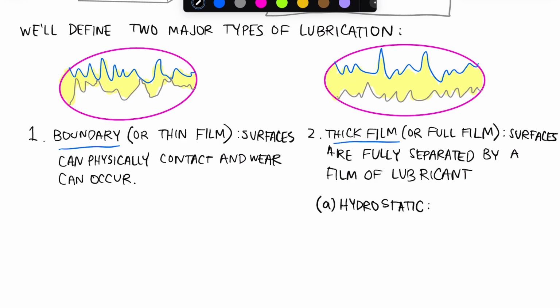So I will link a video of a very impressive demonstration of an air bearing that was able to move, I believe it was 75 tons, somewhere close to that. The way this machine works is it simply forces high pressure air out from underneath the pallet through some nozzles, and this high pressure air causes the pallet to actually float just a little bit above the surface.